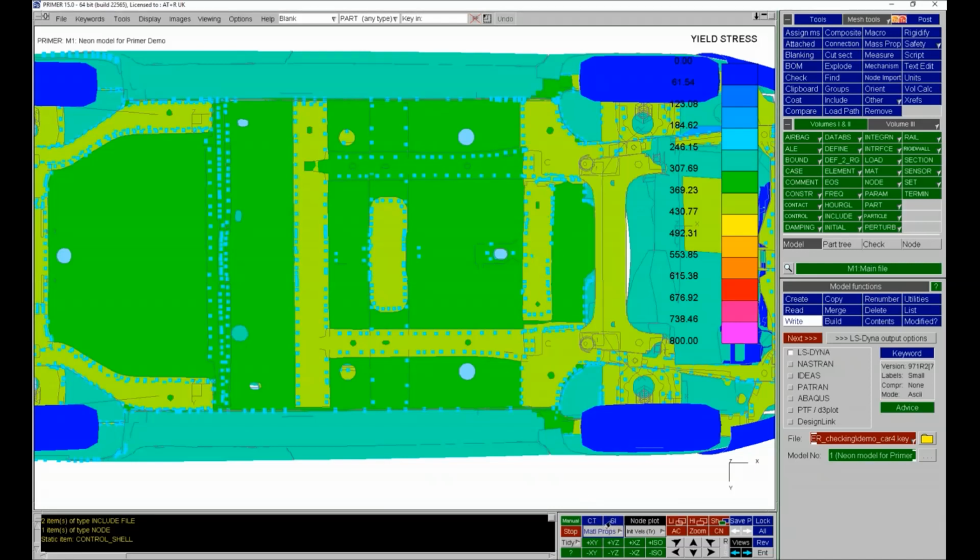Now, next to the blue CT and SI button, there's a node plot as well. So this is for plotting things based on nodes, so things like initial velocities maybe. But also there's tools in here for plotting SPCs on nodal mass. So the SPCs are quite useful. If you use SPCs, or maybe you constrain parts, rigid parts, then you can contour those, and we put a blob on that SPC, all those parts, and it allows you to visually see how they're constrained and in which direction, and whether it's a local or global coordinate system, and so on.